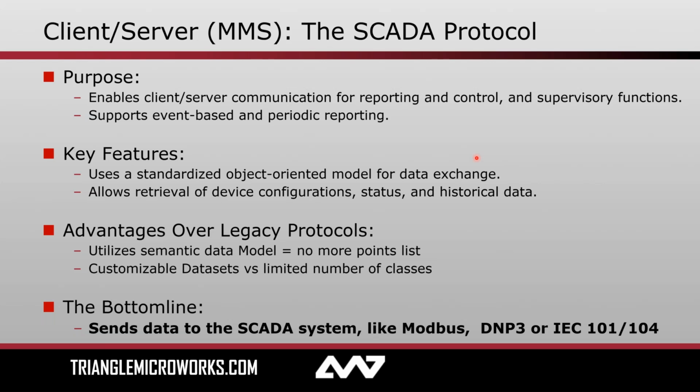But the key takeaways here, it uses our standardized object-oriented model that we spoke about before, our semantic data model, in order to structure these data exchanges. You pick which data you want to send, put it into a data set, associate that data set with a report, and then up top, your SCADA system can subscribe to those reports. Our data sets are totally customizable. You no longer have a limited number of classes that you can put data in like you might have with DNP3.